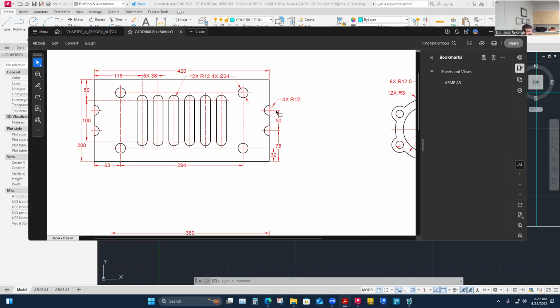But what I'm looking at is I don't love this. You're making me think about that 4x. If I see that, I would need to find in this drawing what that applies to, and they should be very similar features. That 4x definitely applies to these four because they're very alike. This is a 4x by 24 diameter, and essentially the same radius as that, but this is in the diameter. But I don't love that these run together. To fix this, I'd probably pull this 420 dimension up a little higher, get it out of the way, and then create some separation. I could pull this leader line a little bit higher than this one. I do not like looking at this, seeing how those two run together, and they get a little confusing.